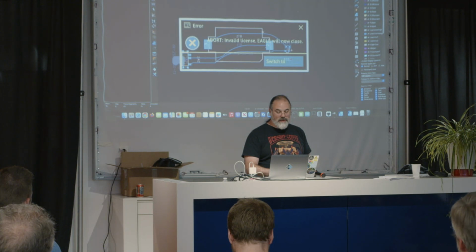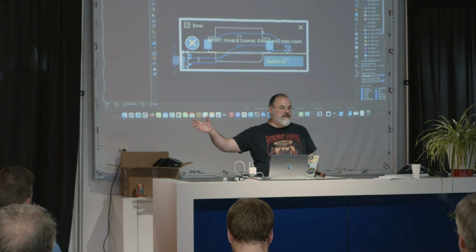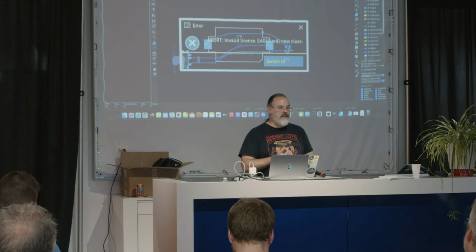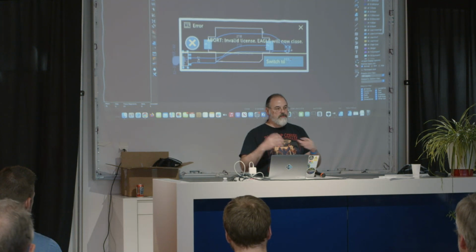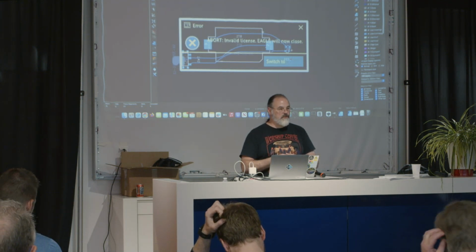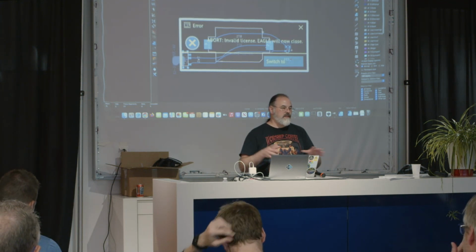But yeah, so if you do want to buy the board, the fabrication toolkit, you click this button, it dumps out everything you need. You just upload the files. It's already got the Gerbers in the right format. It has the position placement data. It's got your BOM. It even references, there's a couple of different ways you can do it, but if you have an LCSC ID for many of those parts that we've imported using that tool, it automatically figures all that kind of stuff out.